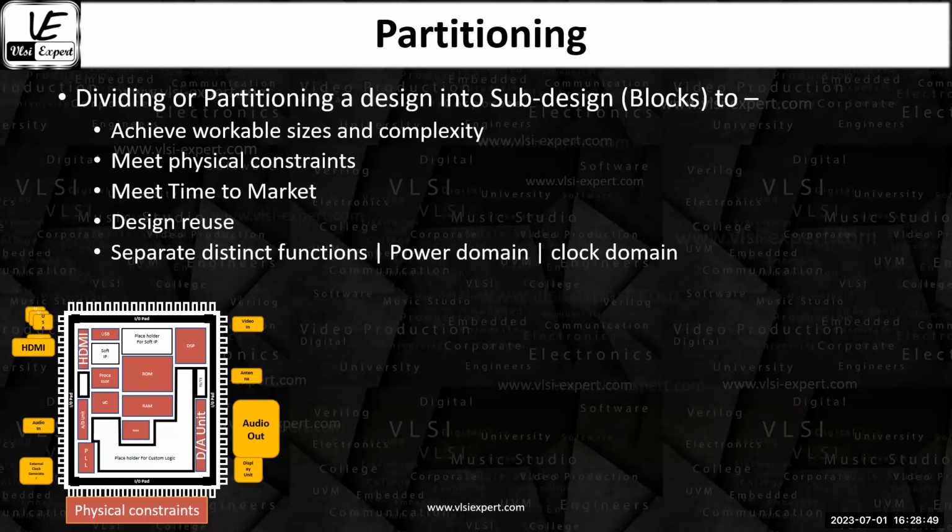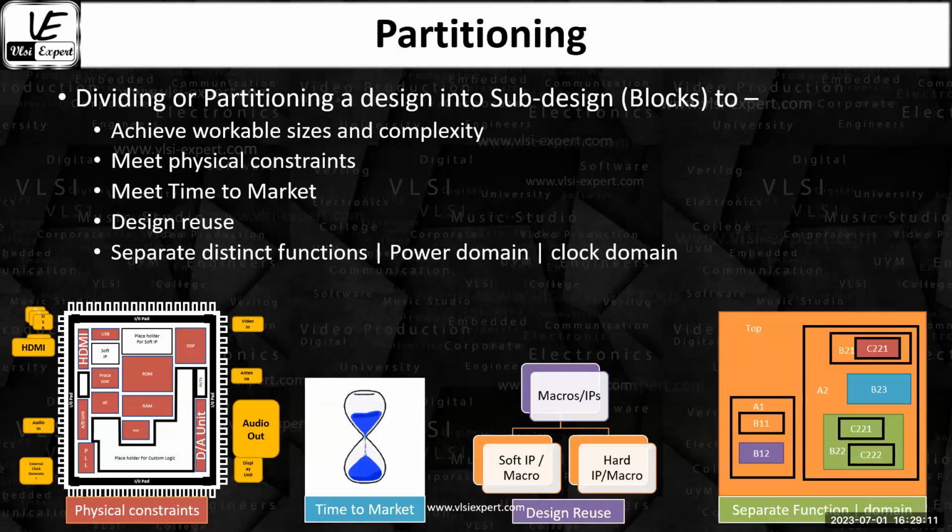So you are dividing the whole chip into different power domains. Same with clock: one portion you want to run at a high frequency, another at a low frequency. That's your requirement, so that means different clock domains. So these are a couple of ways we do the partitioning.